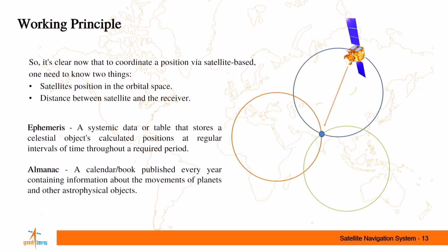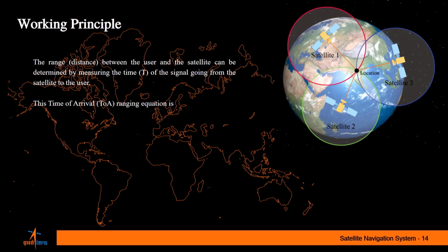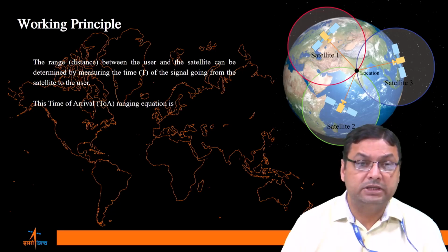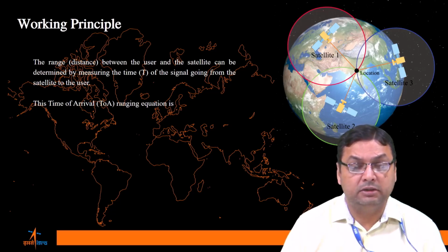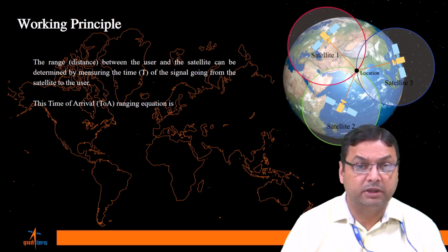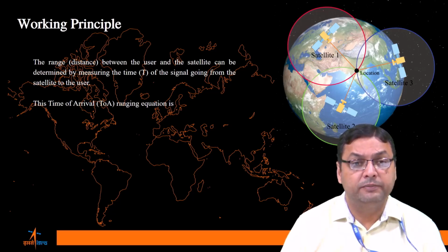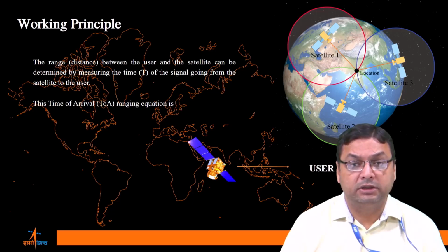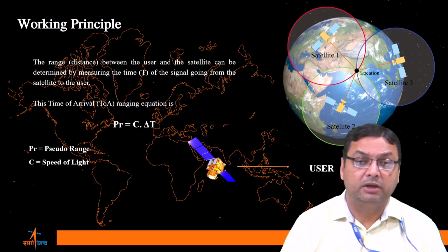So that may be some limited satellites at a point of time, but almanac will provide us the position of all the satellites in the constellation of the GNSS. So it may belong to GLONASS, Galileo, BeiDou, any of the systems which are giving us the global positioning. So here the time of arrival is the important thing, which is taken by the quartz clock, and the time of starting of the signal is from the atomic clock, which comes from the satellite signal. It is embedded in the signal actually, and this will provide us the user location.